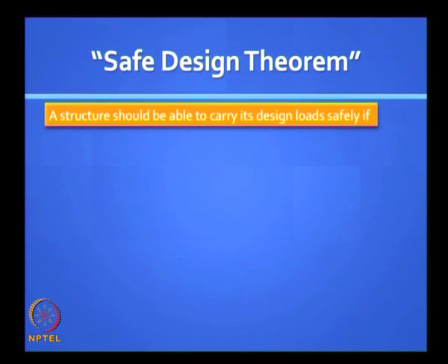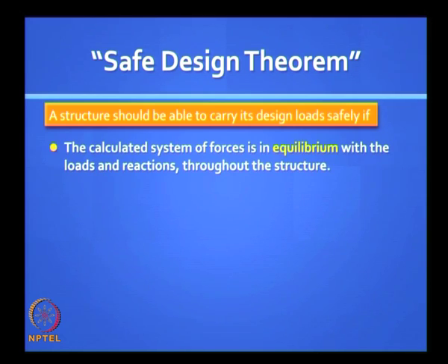But regardless of what you do, it's well known by experienced engineers that if you satisfy certain minimum requirements, you will end up with a safe design. So what are those requirements from a design point of view? A structure should be able to carry its design load safely if 3 requirements are satisfied. Firstly, you must satisfy equilibrium.